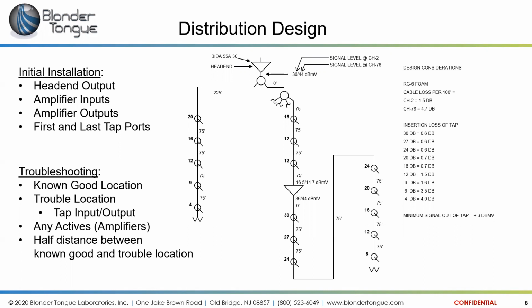Okay, the next question: given high output level minus gain equals minimum input level, if your input is too high, you'll be overdriving the amp. How close to high output minus gain should you be? We say in our full seminars that the minimum input is the high output minus gain. So for these 30 dB gain amps, it will be 14. If you go more than 2 dB above that, because 3 dB is a doubling of power, it is recommended to use attenuators to bring that signal back down. So the range for the input to the amp should be 14 to 16 for the 30 dB gain, or 1 to 3 for the 43 dB gain.